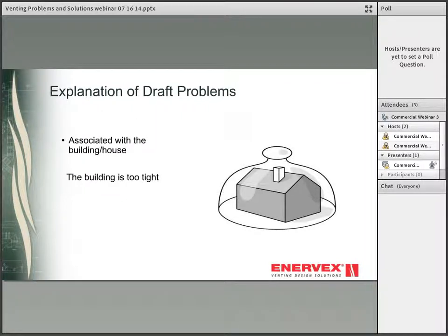A heating appliance needs air for the combustion process. If the building is tight and the proper amount of combustion air cannot be supplied, a smoking fireplace or stove may be the result. If opening up a window or door close to the fireplace solved the problem, an outside air supply should be installed. This type of problem can occur when the house is built too tight to begin with, new and better insulated windows have been installed, or the building has been properly insulated.